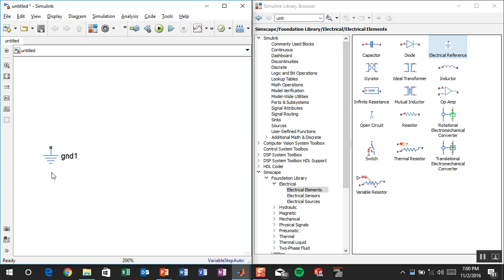When you do SPICE simulation, you can do a DC analysis or a frequency analysis or that sort of thing. You have to keep in mind that, for better or for worse, Simulink thinks in time. So if you're going to do a frequency analysis, you can extract a linear operating point, or identify a model, or actually do a time simulation of a frequency sweep, but it's not quite the same thing.